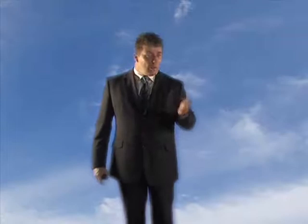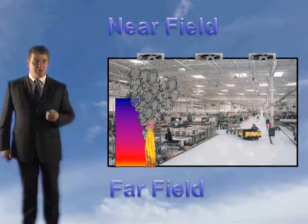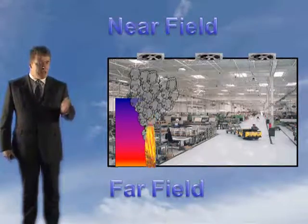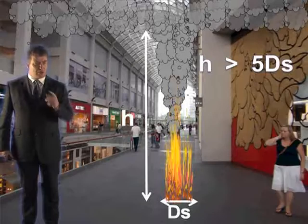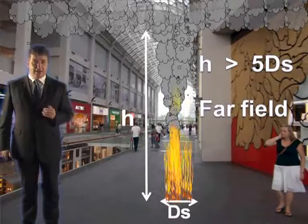Well, as the stores are going to be located covering the whole area, we have to assume worst case scenario and use the model which will result in the greatest mass flow rate. The model, therefore, we're going to apply is the axisymmetric plume. Next, we need to decide whether it's a near field or a far field model depending on the clear layer height. Don't forget, if the clear layer height is greater than the longest dimension of the source multiplied by 5, then it's deemed to be a far field model. If not, it's a near field model.